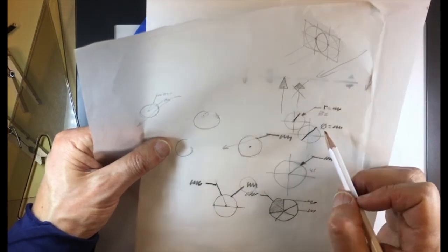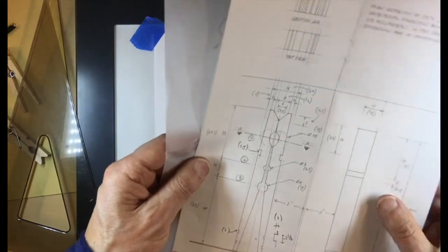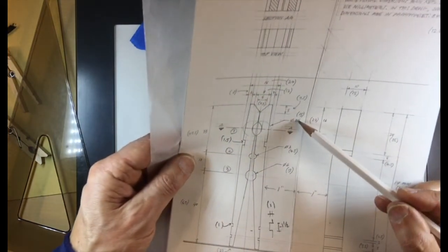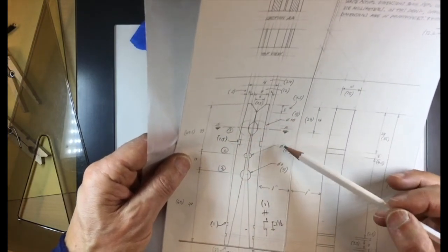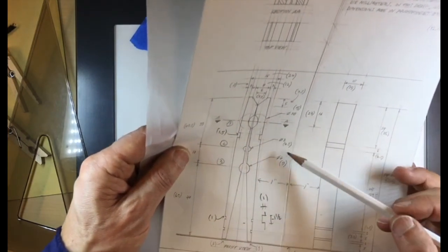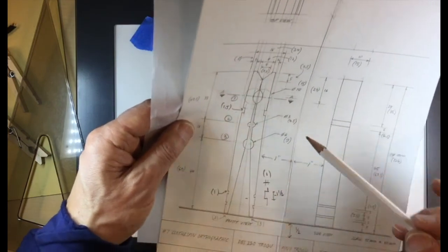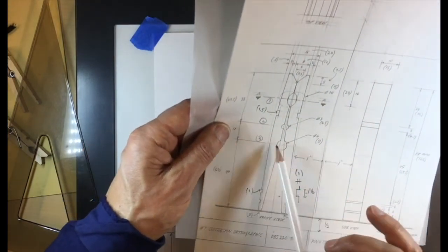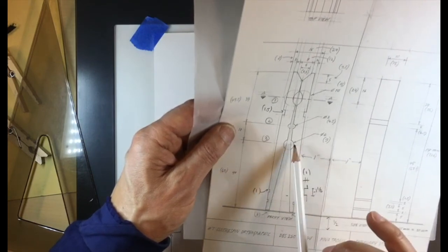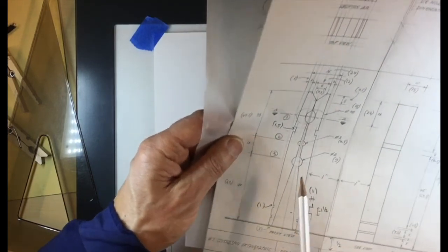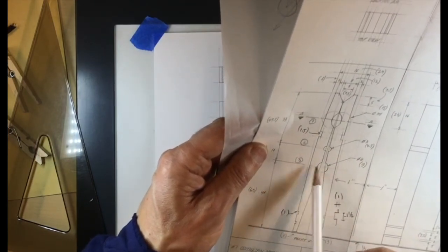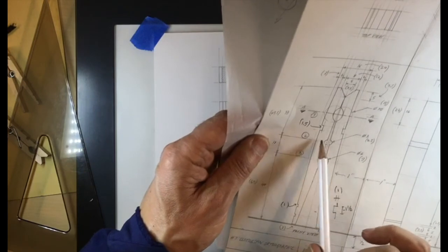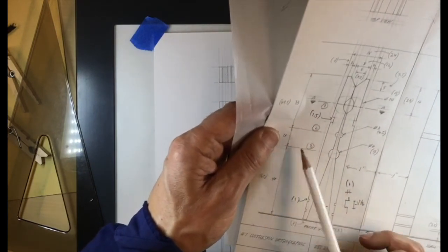And these are now real, okay? 10 is the real diameter, 10 millimeters. So you would label it as such, 3 millimeters and 6 millimeters. And on the other ones, what you do is you draw dimension lines from the point that you're measuring, but you don't really need to go all the way to it. You just go close to the object. And then you draw extension lines, and then dimension lines, and you put little arrows.